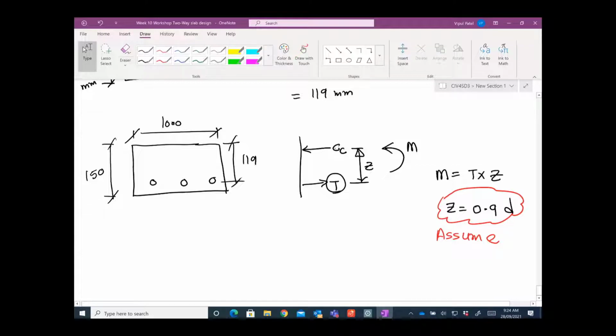You might get the conservative answer, but look, this AST that we're going to calculate would be approximate. It is not correct, because you're going to check your minimum reinforcement, you're going to check the shrinkage, and so this 0.9D is going to save your calculation time. Of course, when you want to optimize, and again, there is a second assumption as well, that this slab design does not govern by bending,